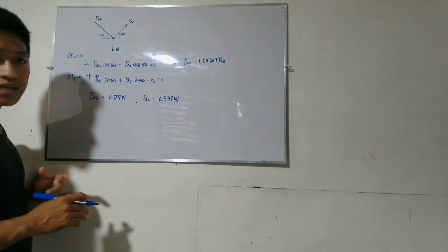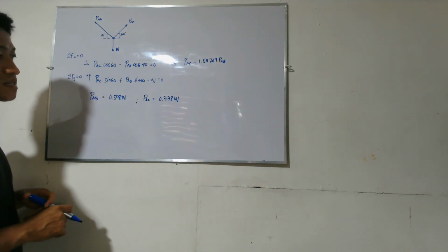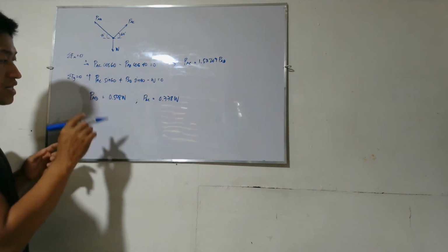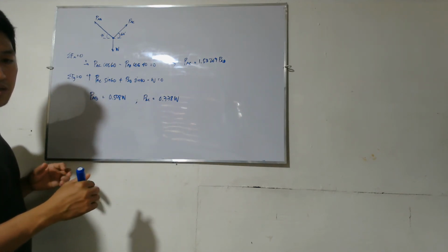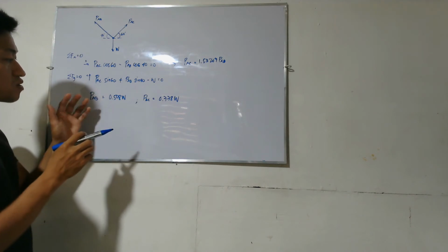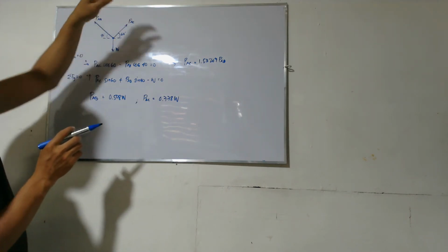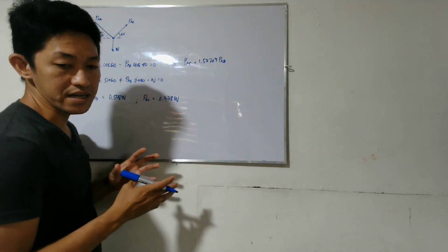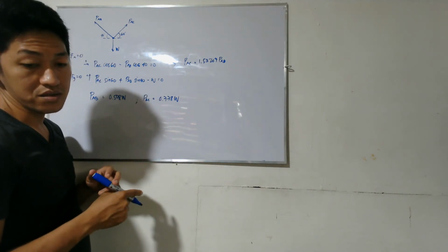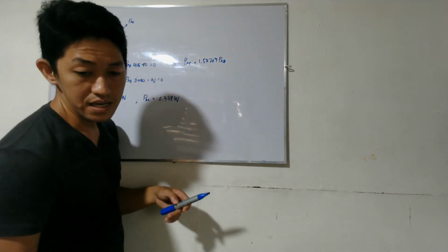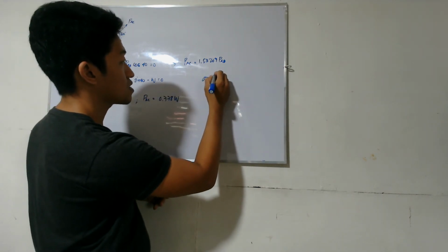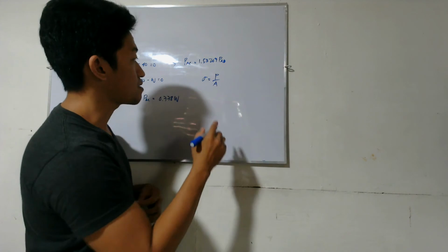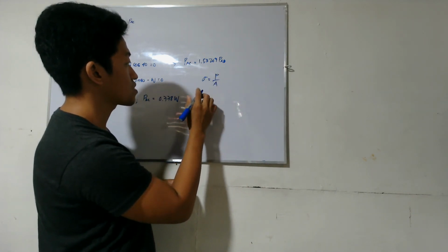So, the next step is that we need to use both of these equations, because if you use only one, you get a value of W that is fine for AB but AC will fail. Meaning they have different allowable strengths, so we need to use both. And then, using these equations, we will get W.